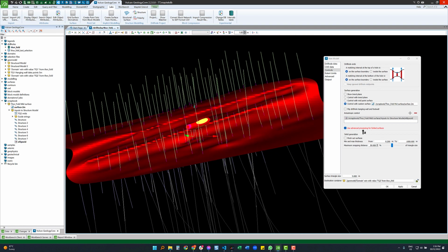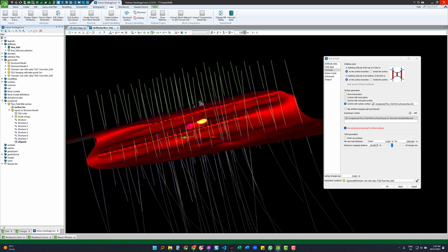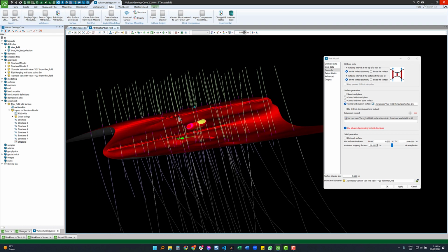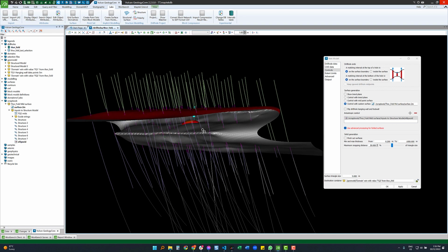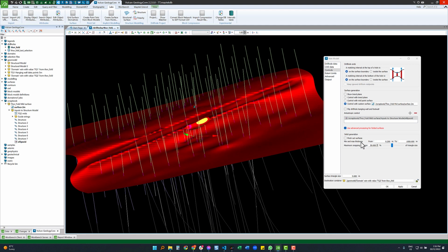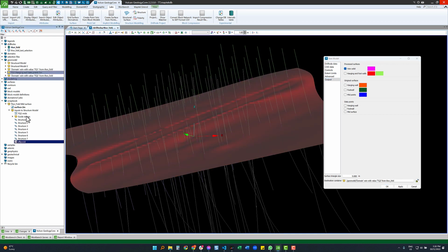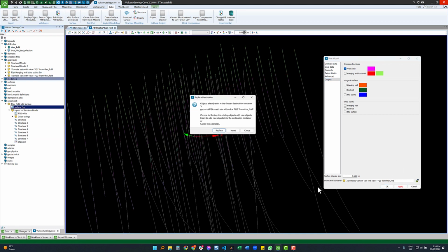We want it to process them properly, and it's also going to then use this mid surface that we provide to define the hanging wall and the footwall contact points based on which side of this surface they are. So anything that's on this side is going to get flagged as hanging wall, anything that's on that side is going to get flagged as footwall. So that's how it works. I don't need to pinch it out because it's not going to cross in this scenario. I'll give it an extrapolation distance of 10 meters. And this time I'm just going to make a vein solid. So we'll remove bits and pieces and I will press apply.